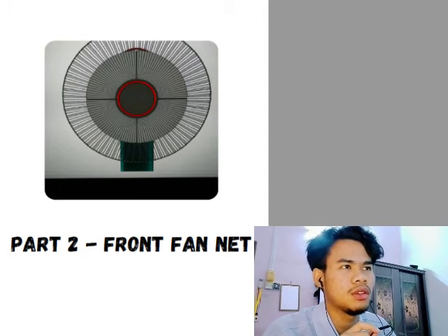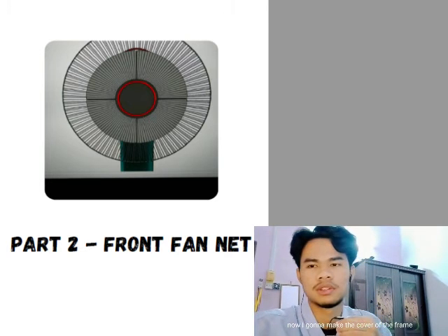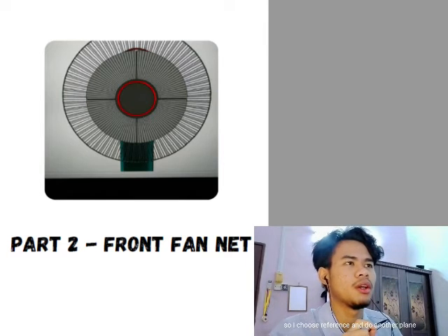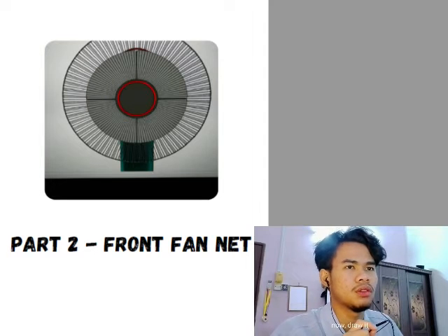Okay, now the frame is complete and it's using stainless steel. Now I'm going to make the front cover of this fan. So choose reference and do another plane, but make it close to the fan and confirm it. Now draw it. Okay, sketch. Do another circle. Limit a bit. Confirm features and extrude boss. Yes. So make it 20mm in front and confirm.